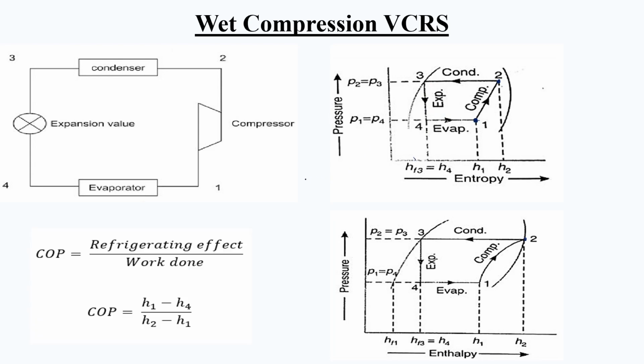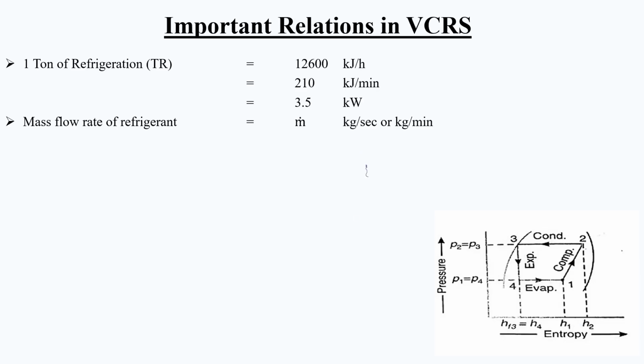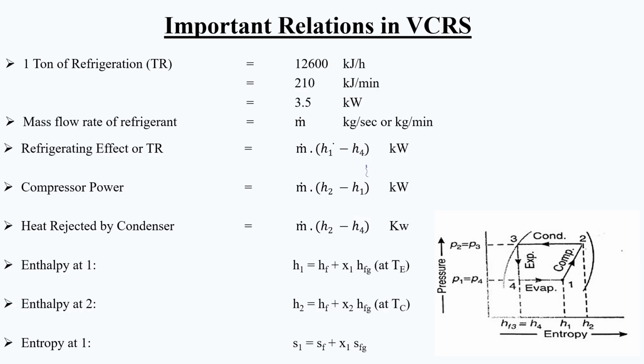There won't be any change in COP. That will be nothing but the refrigerating effect, H1 minus H4, divided by the work done, which will be H2 minus H1. Then the important relations are the same; the refrigerating effect also will be the same.